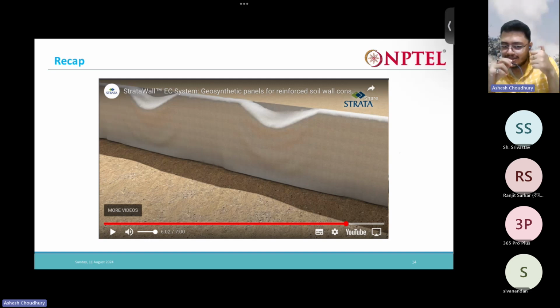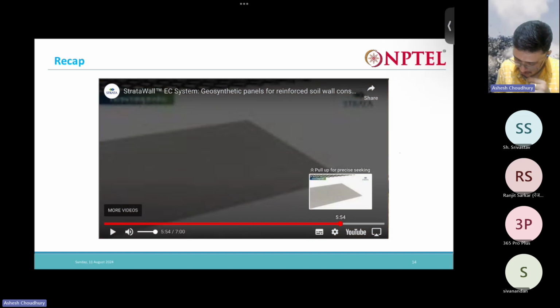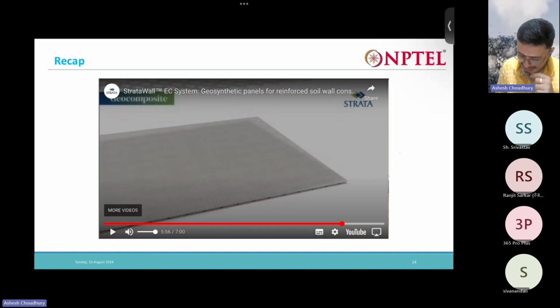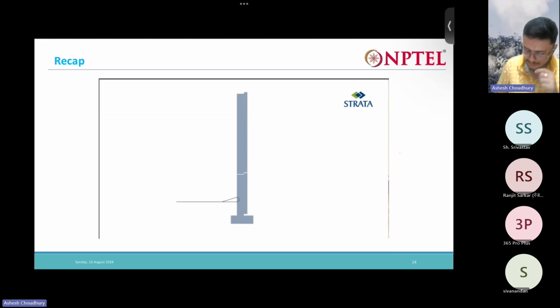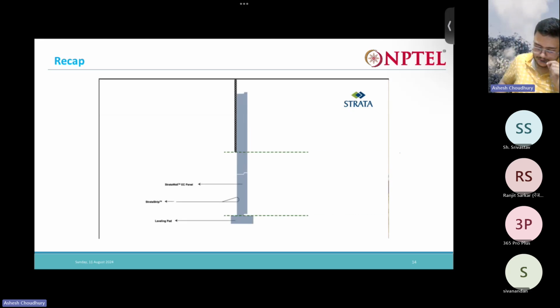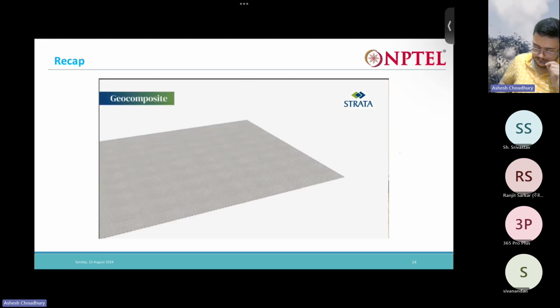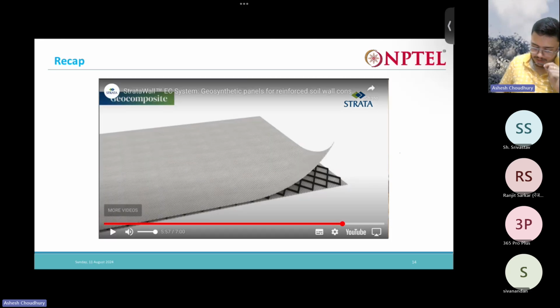One is your non-woven geotextile and also the geonet you are using. So see this. It is a sandwich kind of thing, right? The geocomposite should be placed next to the panel fascia, above ground level, as per the drawing. One layer of non-woven geotextile, then we have geonet, and over that again we have the geotextile. That's why it is a composite of two types of geosynthetic. That's why it is known as a geocomposite. And this geocomposite will act as both a filter and a drainage.